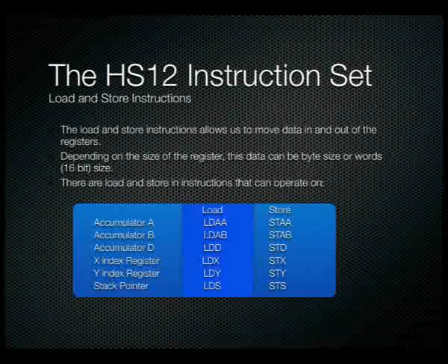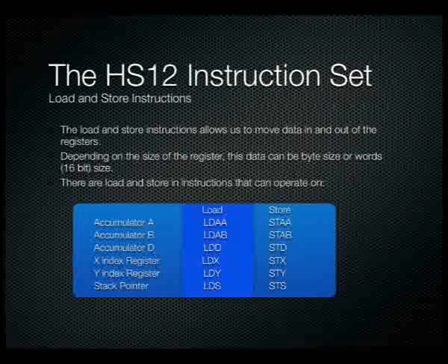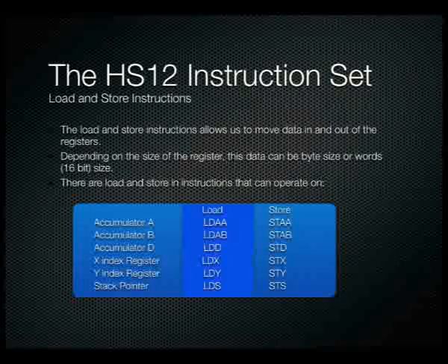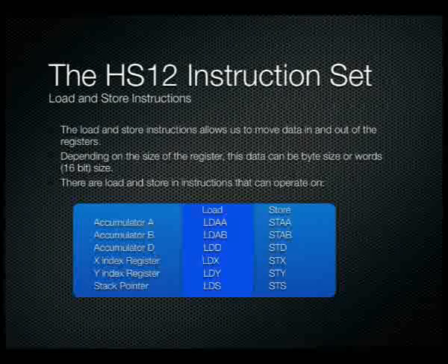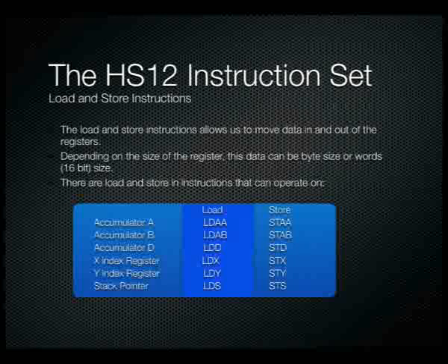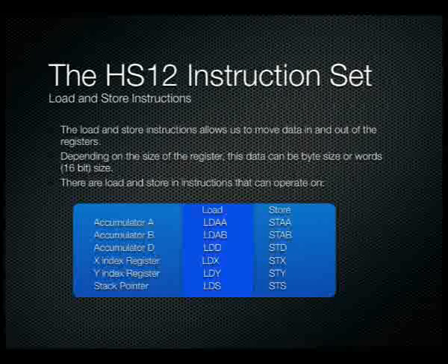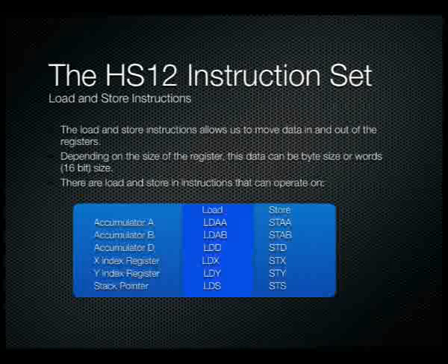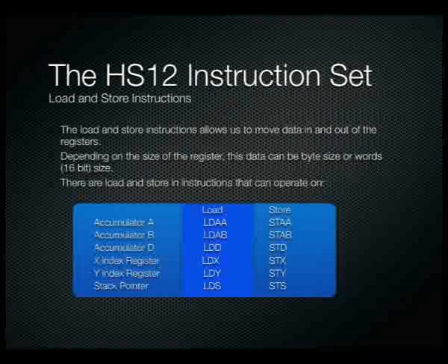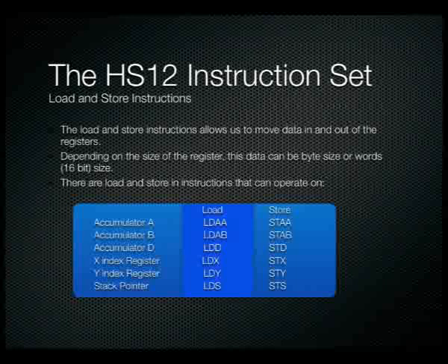When it comes to loading our data, we have the commands which have LD in front of them for load. LD stands for load, and then the next one or two letters define the register. We've got LDAA for accumulator A, LDAB for accumulator B, LDD for accumulator D, LDX and LDY for index registers, and LDS for our stack pointer. One thing to keep in mind here is that the A in the accumulator name defines it as an 8-bit load, whereas if it doesn't have an A, like LDD, then of course it's a 16-bit load.